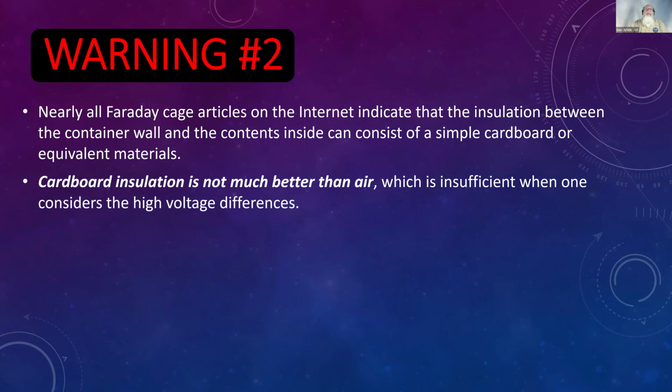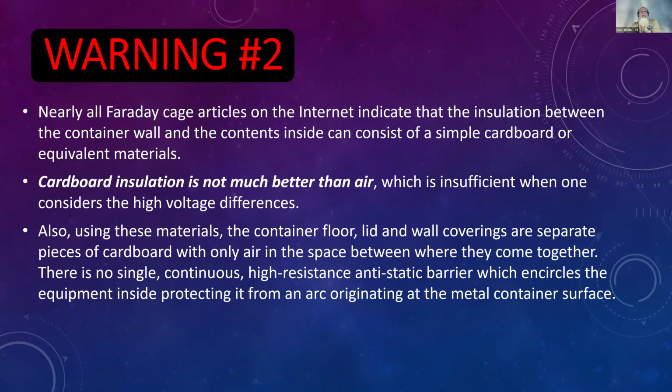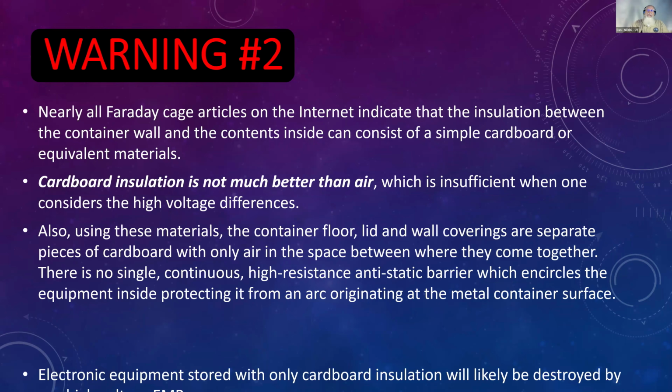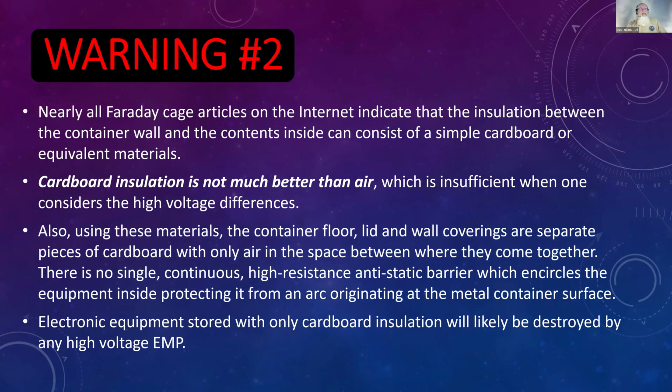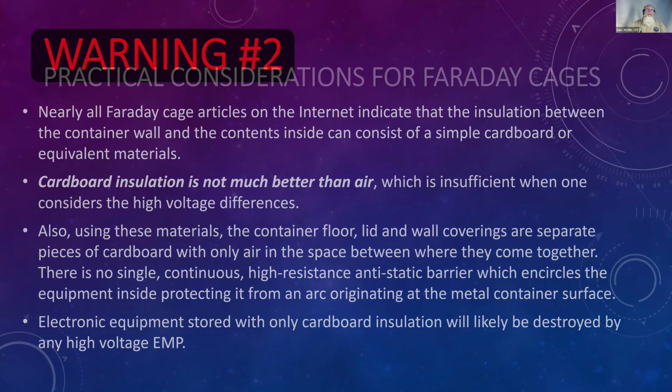Cardboard is not much better than air, and you will get a 5,000 volt arc between the contents and the inside. So you've got to make sure that we are using material that's at least 1 inch, preferably 2 inches, all the way around to separate the outside skin from the inside, plus using your anti-static bags. Without that, your equipment will be fried.